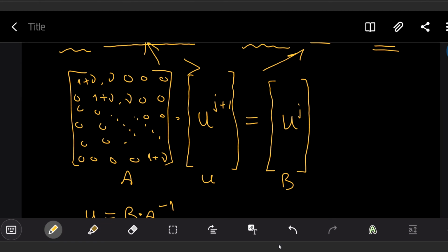You can know it from your previous experience, but when you switch from one task to another, this value changes. So try different Courant numbers, try to have as big as possible until your flow starts to crash, and then you will know the physical limit of the Courant number that can be used.